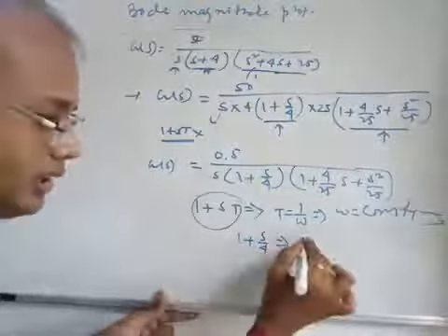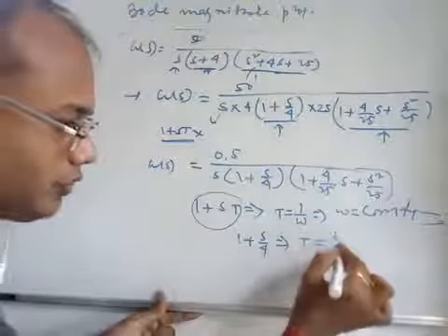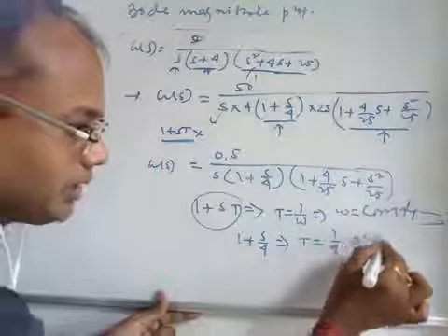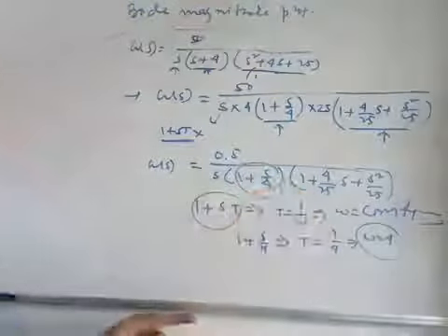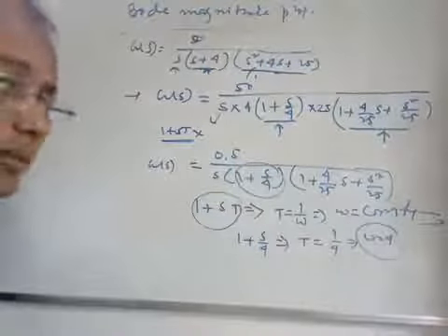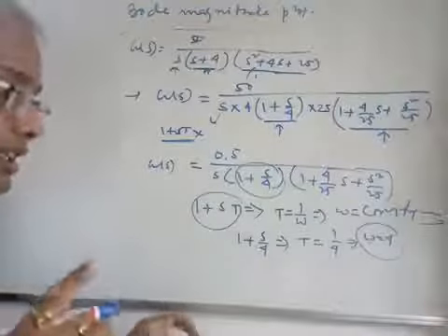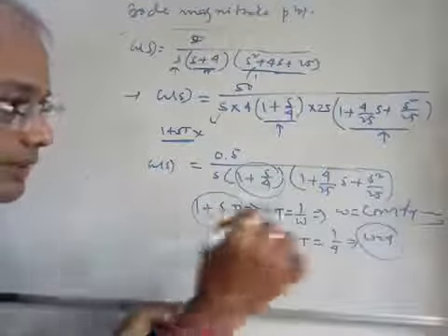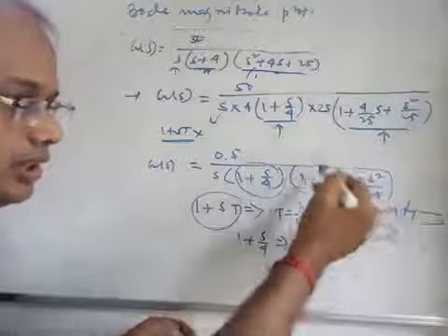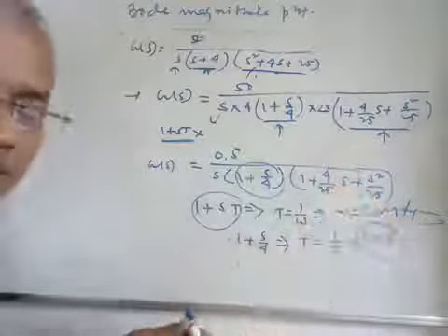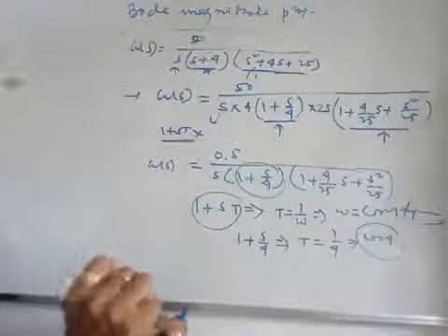So here you get t is equal to 1 by 4, which means omega is equal to 4. For this factor it is very simple to get the corner frequency, as the previous method we have already discussed in the last class. Now see that this is your second order factor. So what is the corner frequency corresponding to this factor? That is the newer concept here, right?